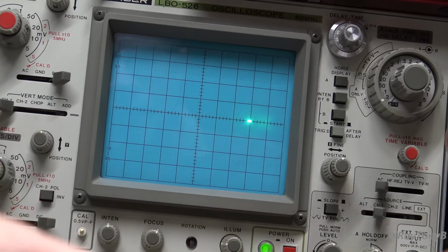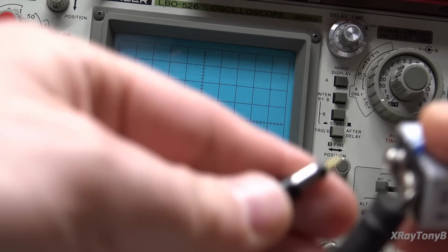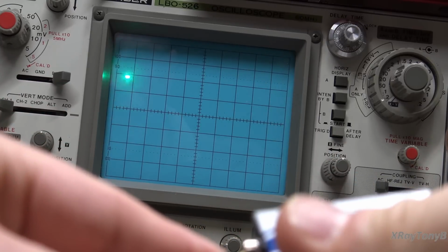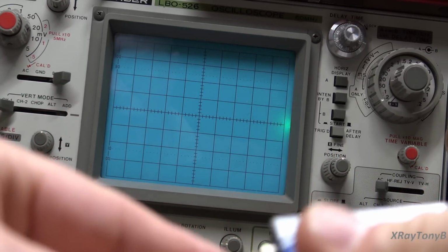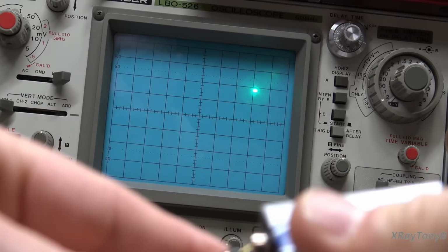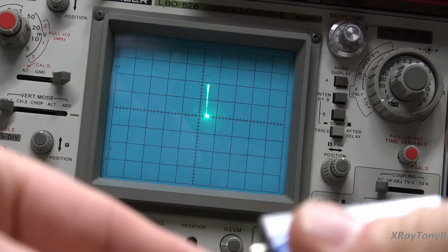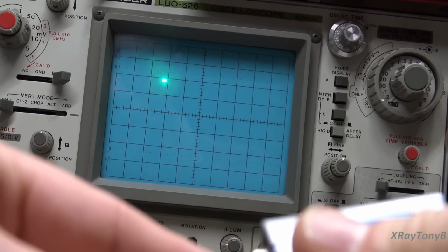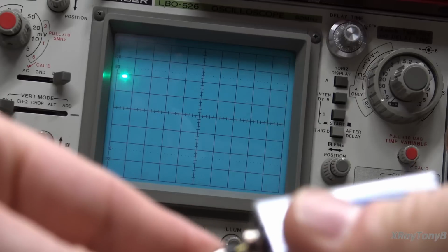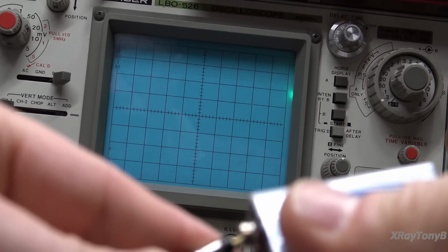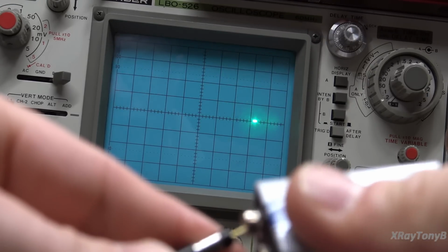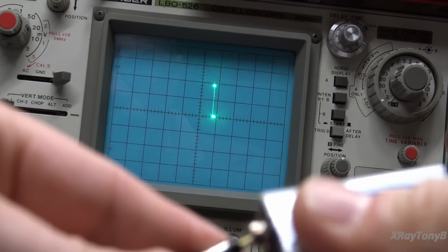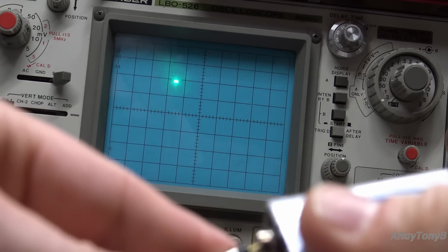So again, when the voltage is there, it goes up. When it goes away, it goes down. So see? And I can turn it on and off. And right now, I'm just turning this on and off. Now, this is not alternating because the voltage never goes less than 0 volts. It always goes 0 volts and positive volts. It never goes to a negative voltage.